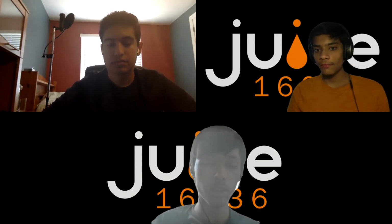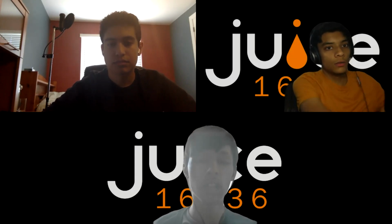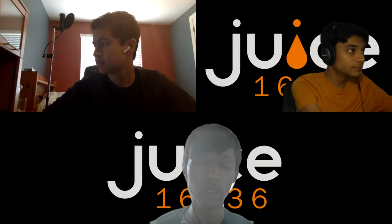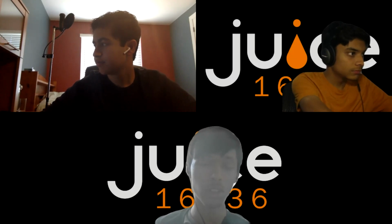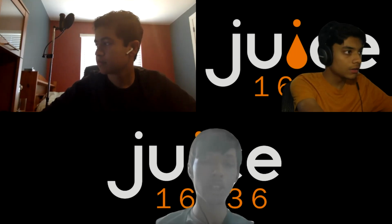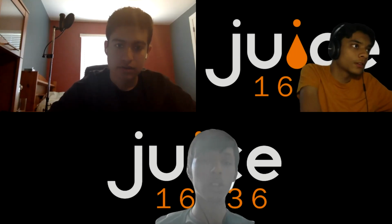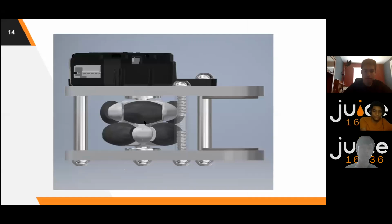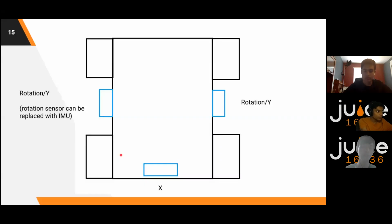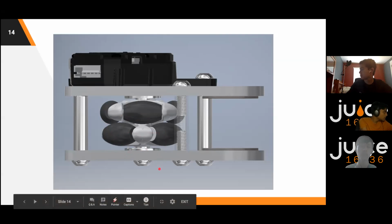Say your wheel is oriented such that the roller is not perfectly in contact with the ground, then you're going to get inaccurate tracking, and it could also introduce some resistance if the rollers aren't on the ground at all times. So when you use a double stack of omnis, the rollers are alternating, so there's always going to be one roller in contact with the ground. And generally, you'd want the wheel with as many rollers as you can get, because that will get you the most circular wheel possible.